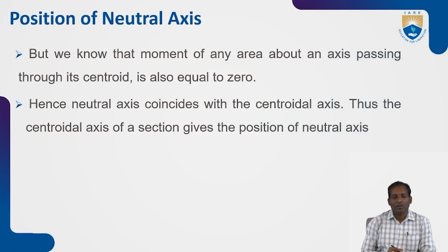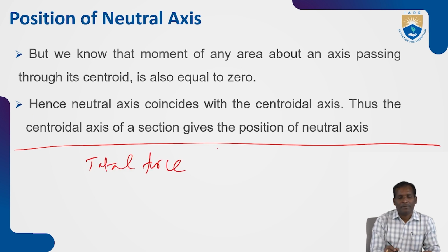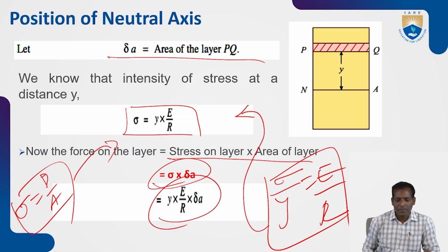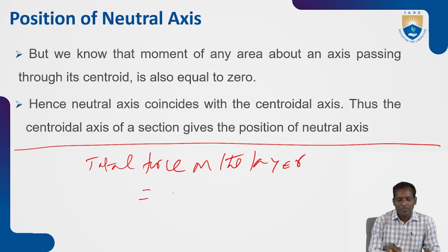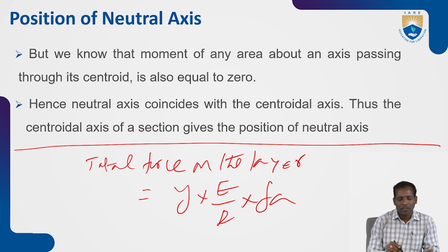So how do you calculate the total force on the layer? You know the individual force on the layer is y into E by R into delta A. So integrate, and you will get the total force.